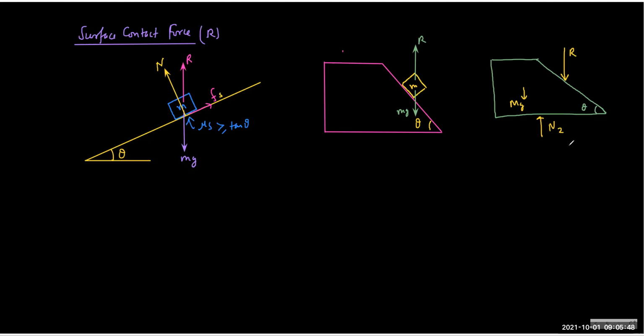the wedge is already in equilibrium because there is no horizontal force, and therefore the F required to keep the system at rest is 0. You need not apply any force; it will remain at rest. Don't worry.